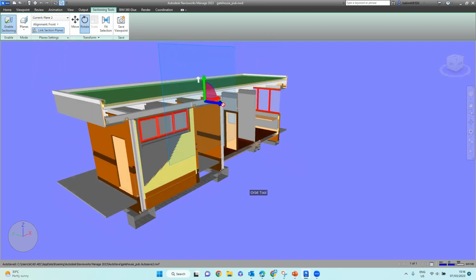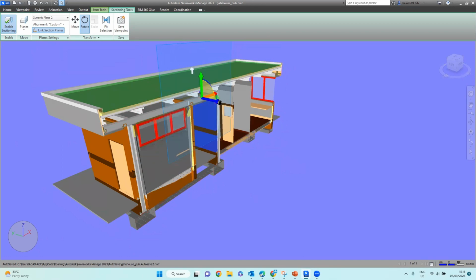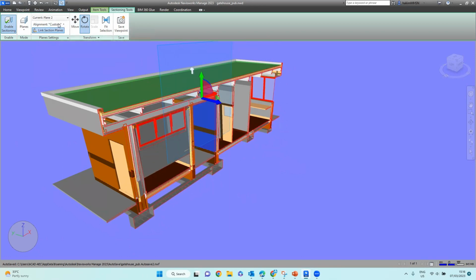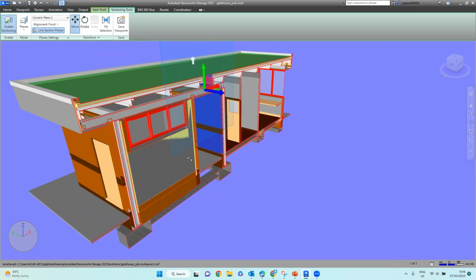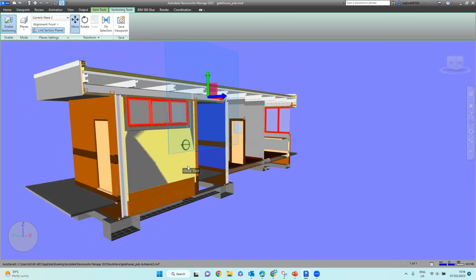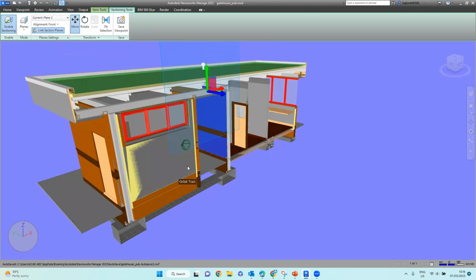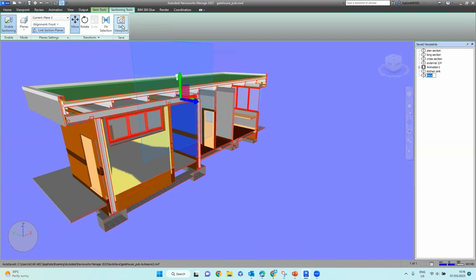And then let's say there are some important things that you want to note in this view. So we will use viewpoints. If you look at this panel, we have save viewpoint. You can click it here and it will bring up this save viewpoint panel.